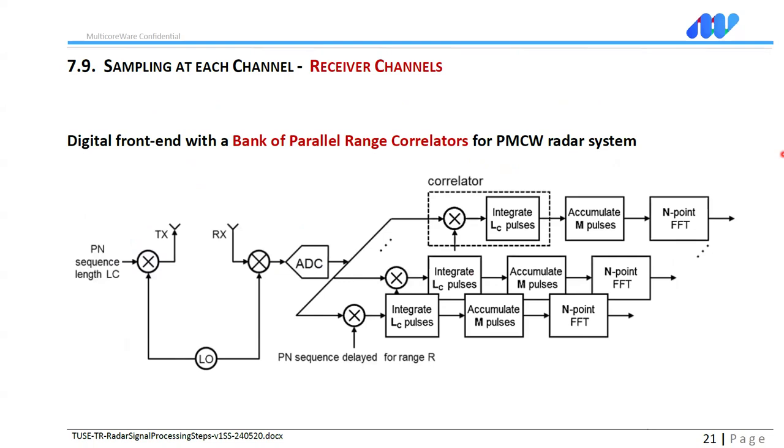And the third dimension is where we have multiple antennas. We will collect signal from multiple antennas. So the first two sampling domains are the fast and slow time domains. They're temporal. That's a function of the time variable. And in this slide, we see the utilization of different transmitters and receivers. So sampling using different antenna terminals is taking place, and each antenna is located at a different position.